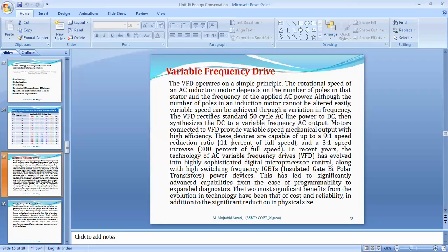So nowadays, I think you are much more familiar with the inverter AC. Inverter AC does not mean it works on an inverter; rather, it is fitted with a variable frequency drive. Once the temperature is reached, the speed of the blowers or the compressor is reduced with the help of the variable frequency drive.